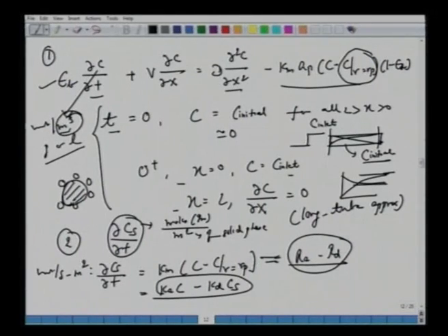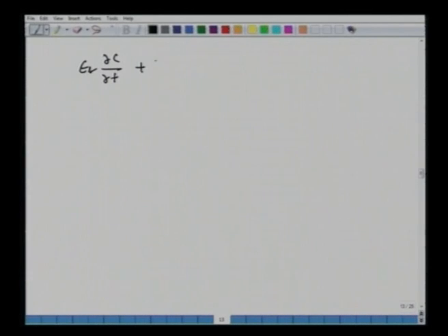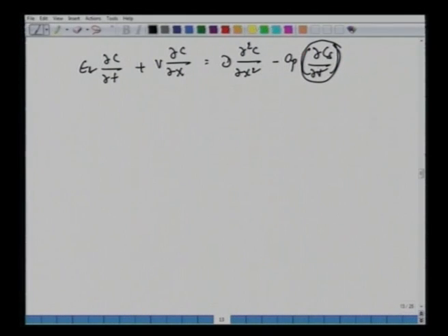Alright. So going back to the first equation, we can write epsilon_b ∂C/∂t plus v ∂C/∂x equal to the dispersion or diffusion term, and here you have the flux. Now that flux is nothing but the rate at which the solid phase concentration changes. Notice this is a flux we had equated to the rate of adsorption and desorption.